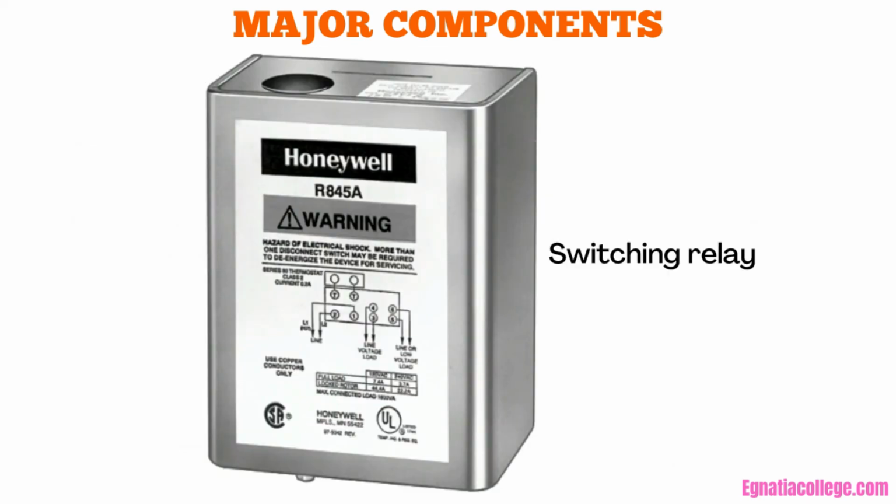Switching relay. Used between the low-voltage wiring and line-voltage wiring. When a low-voltage thermostat calls for heat, the relay pulls in, closing the line-voltage contacts on the relay, which turns on the main power to the furnace or boiler. Usually they have a built-in transformer that provides the low-voltage class 2 control circuit.